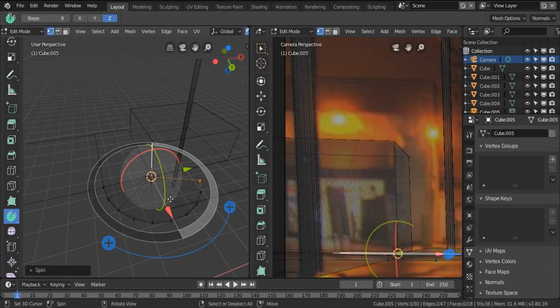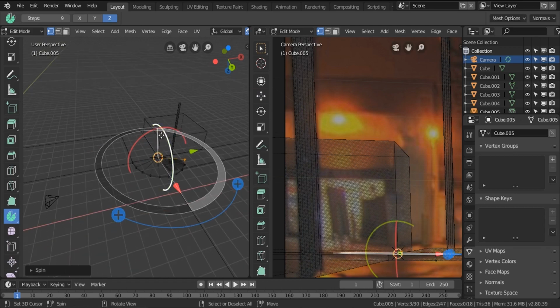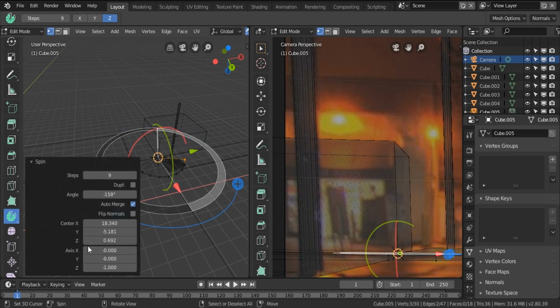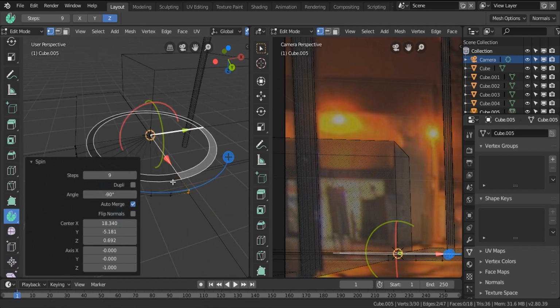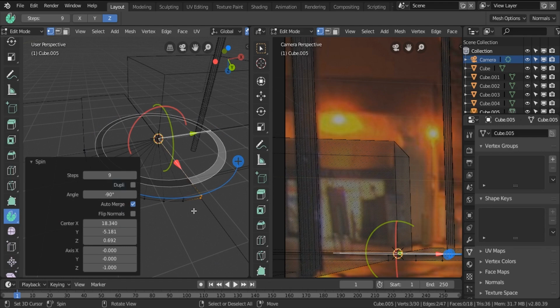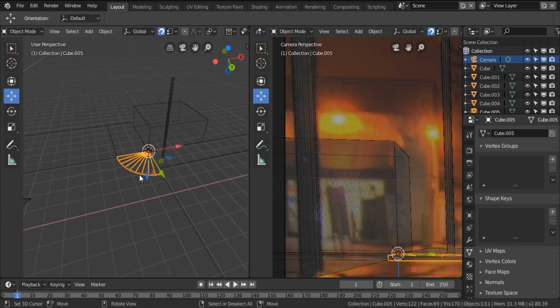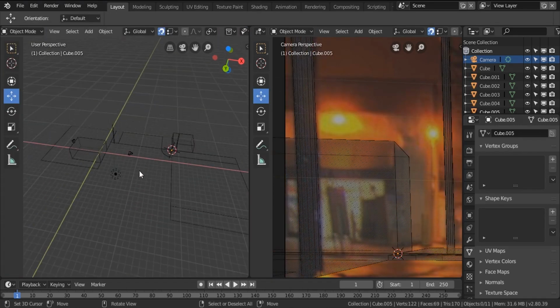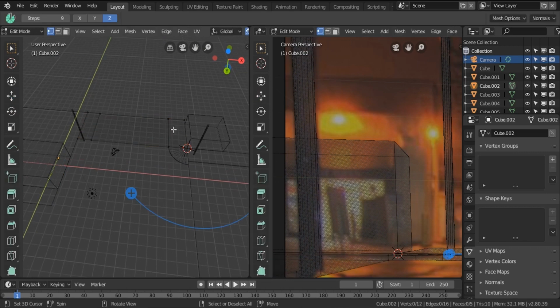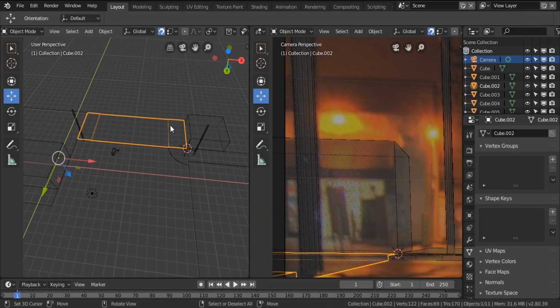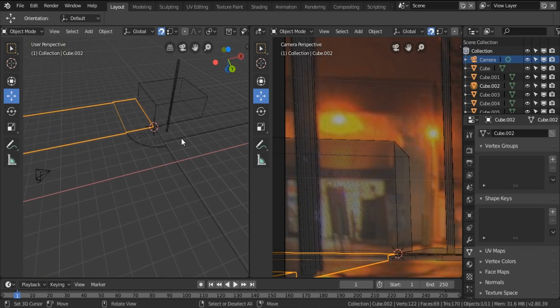Yes, but we have a problem, which is that we didn't make this street sidewalk street even. So I'm gonna be solving it just in a moment. Let me change this one to -9 degree. There we go. I would like to keep this one at 9. That's fine. Okay. So here, you can see that this part over here is bigger than this part. And that's what's causing us this problem over here.